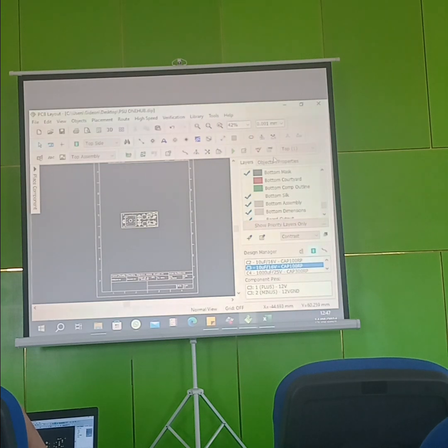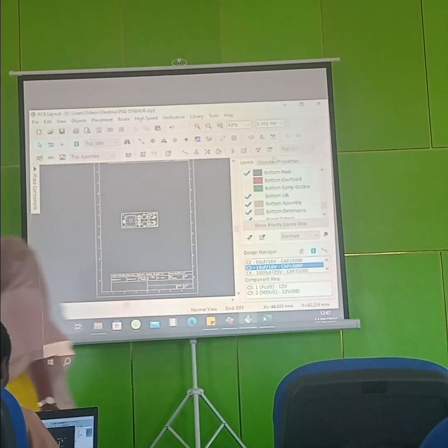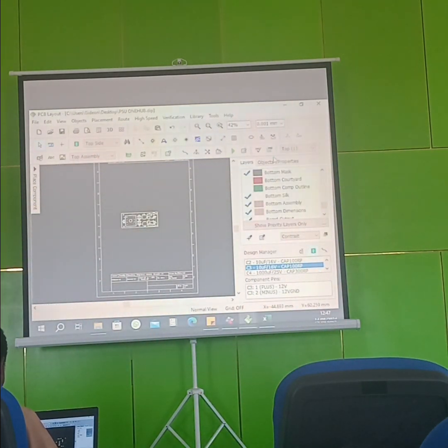I want to see it in a folder. How many files? Gerber file with drill file, pick and place file, STEP file, and what? BOM. You should both import and export. No, export it. Import is when someone sends the file to you and you want to open it on your system. Export is when I want to send it out to a fabricator and to a company that will place the component and make an order for the component.